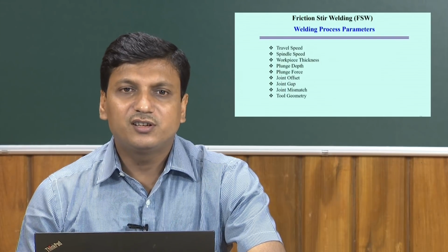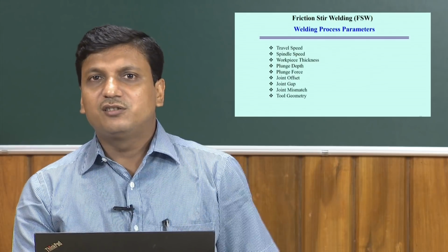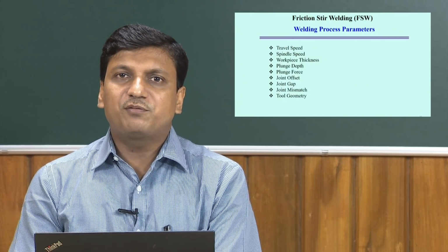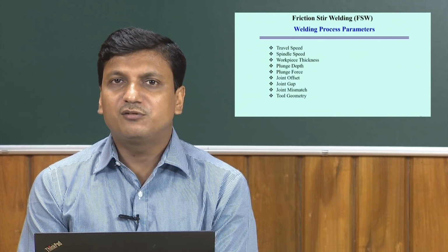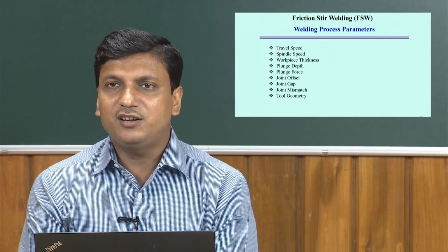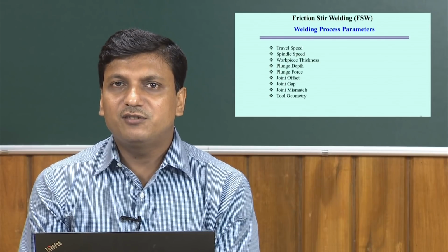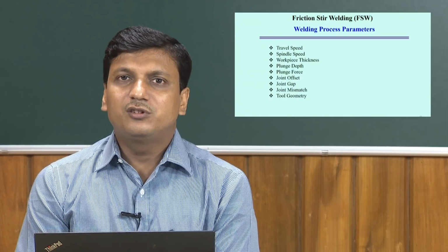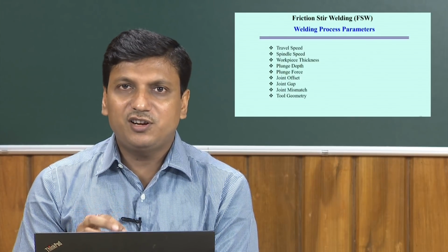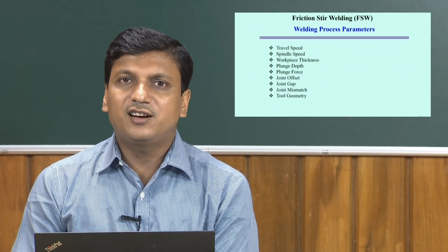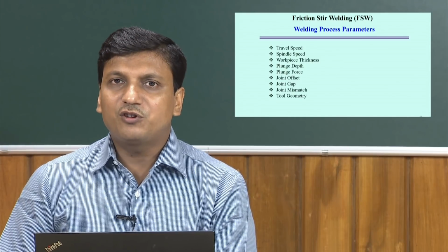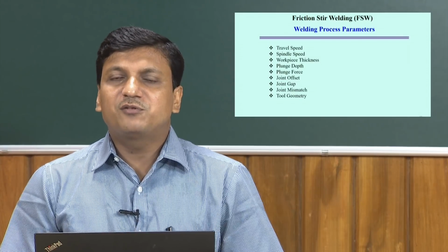Third parameter is the workpiece thickness. If workpiece thickness is very high, it is very difficult to plasticize the material exactly at the bottom of the workpiece plate.